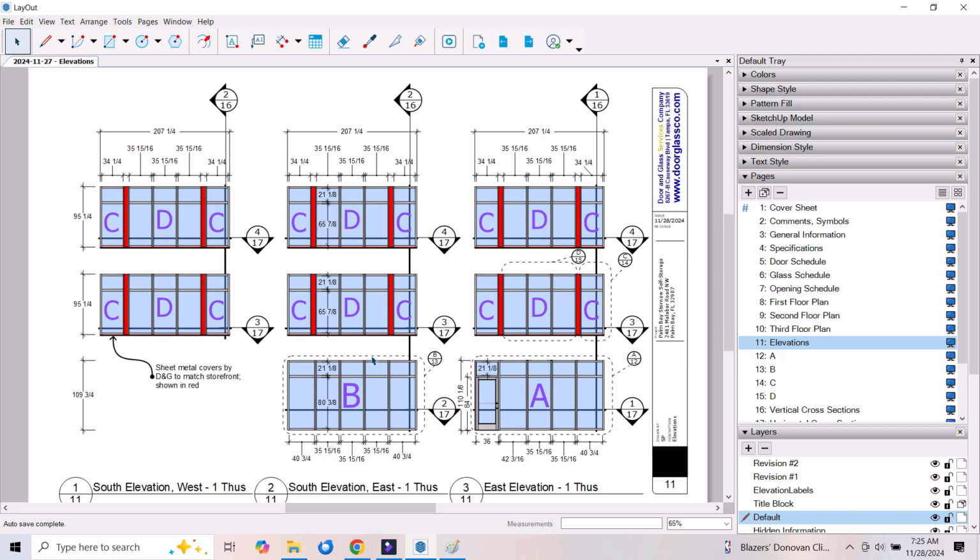When we have openings stacked vertically on top of each other and we want the mullions from the first, second, third floor to be aligned with one another, you can't just put the frame in the opening and center it. You would want to look at what's above, what's below, where's everything going, how's it going to align. So for that reason, I included a page in this drawing set where we're showing these elevations relative to one another.